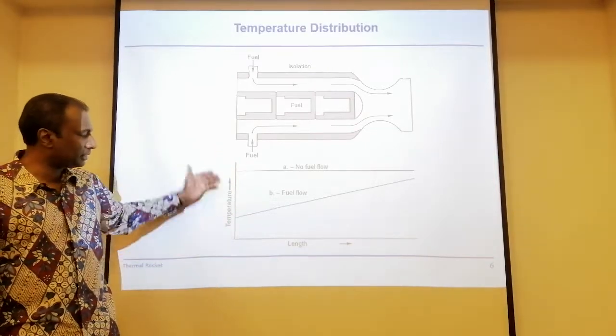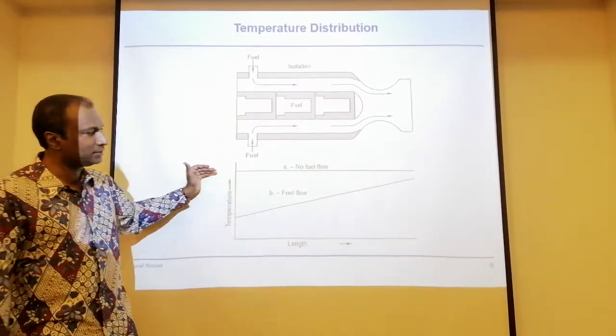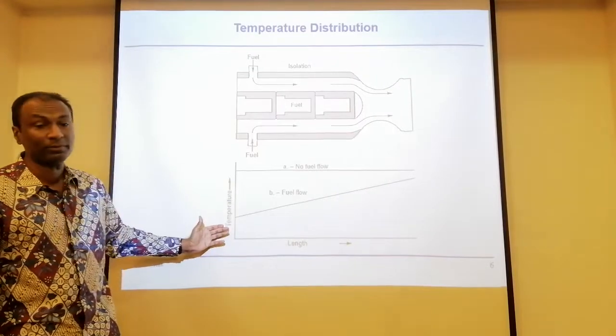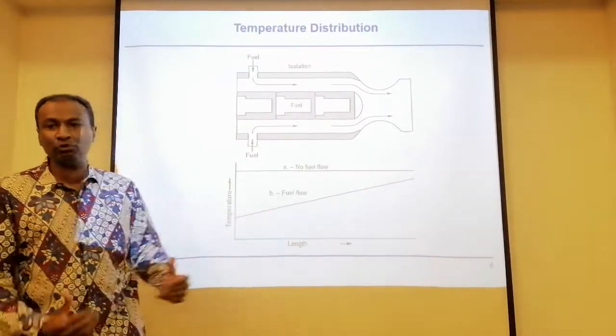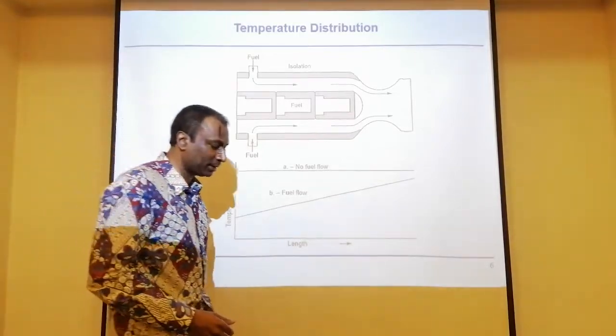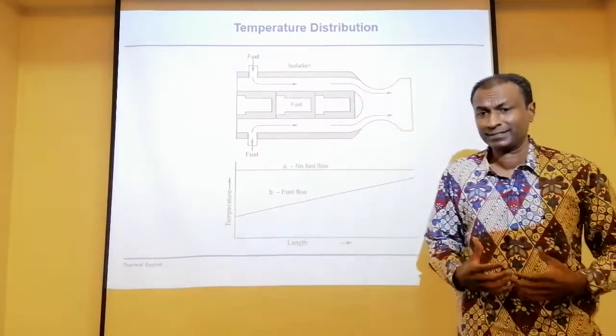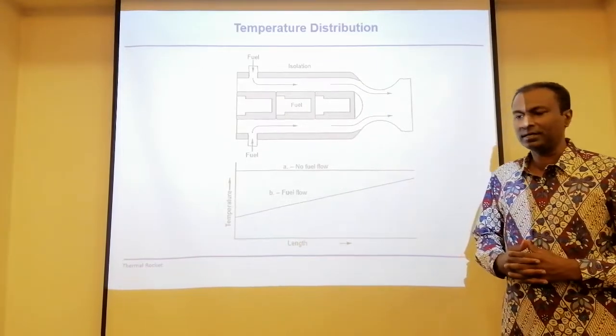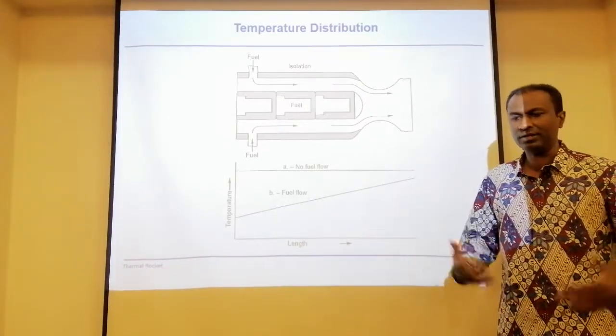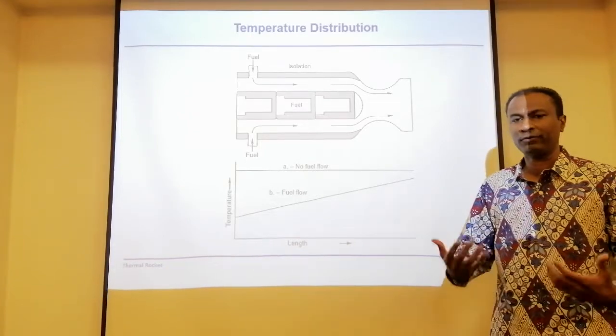If you look at the temperature, when there's no fuel the temperature is so high, but with the help of the fuel, you are not only cooling, but you are also preparing the fuel to be injected into the combustion chamber. So it's a win-win situation, so to say. You are not losing the heat, but you are reusing the heat to prepare the fuel before you burn the fuel.